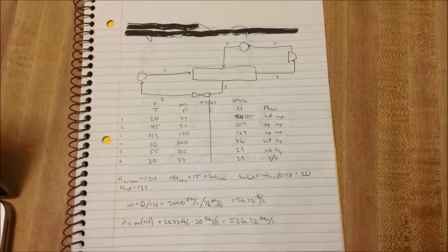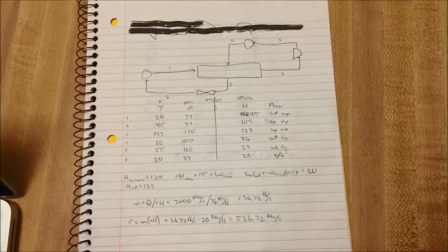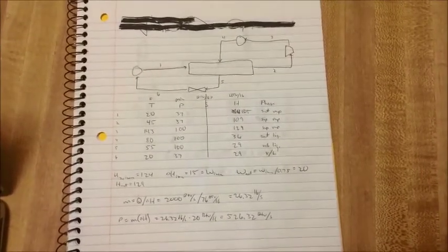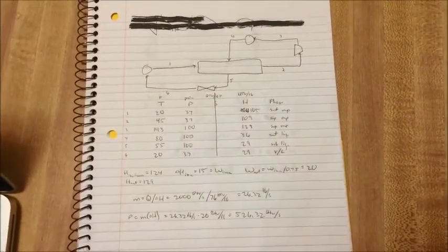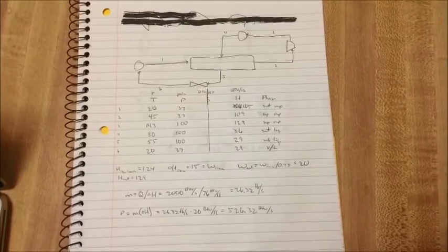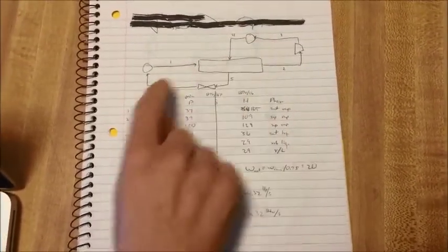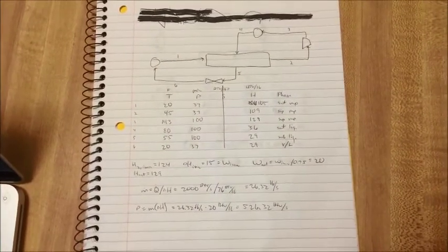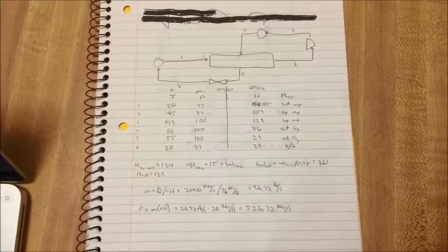In order to solve the countercurrent heat exchanger refrigeration cycle by hand, there are several key assumptions we must make. First, we assume that the evaporator and the condenser each operate at constant pressure. Because of this, if we know the pressure of the exiting streams, we also know the pressure of the entering streams, and vice versa. We can find this pressure with the knowledge of the temperatures at which they operate, using the pressure enthalpy diagram.